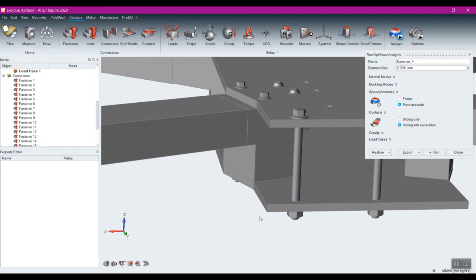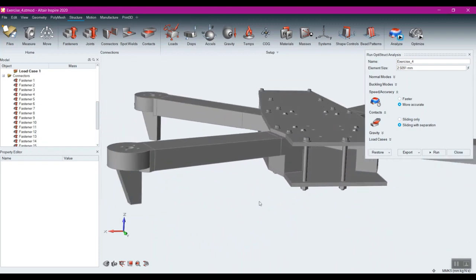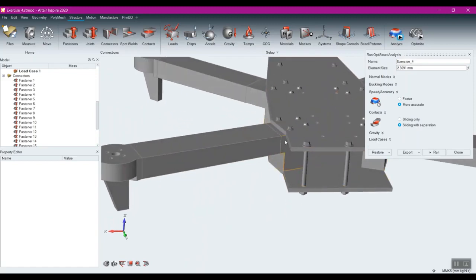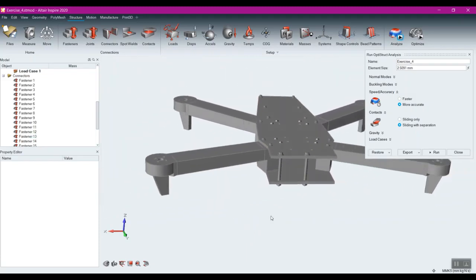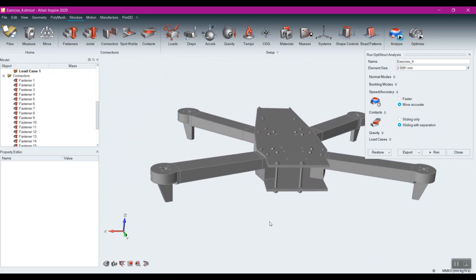The reason why it's not on by default, and the one slight downside to it, is constantly then calculating or taking a look at the forces in the areas of contacting surfaces. I've only got 8 of them on this model, so it would not affect the analysis time too much in this case, or barely at all. But if you had many contacting surfaces in your model, it could potentially increase the analysis time.